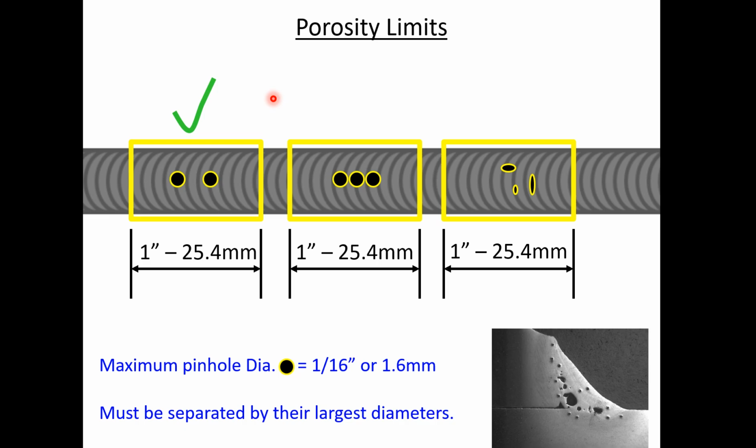welded over. Now, there's going to be people in that room, right there, right now, who have decided many years ago, maybe you've been doing this for decades, that when you see porosity, you just weld over it. I want you to know one thing. It's not gone. Yes, you've made it disappear. I get it. And the customers would prefer for their e-coat conditions to make sure that there's as few as possible. Remember, e-coating is less than effective if you can't get the paint all the way down inside the holes, and it's very difficult to get it all the way down inside these porosity holes. So they prefer them not being there. But you cannot just weld over it.